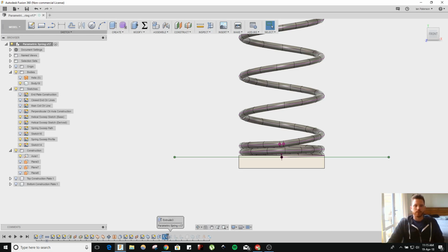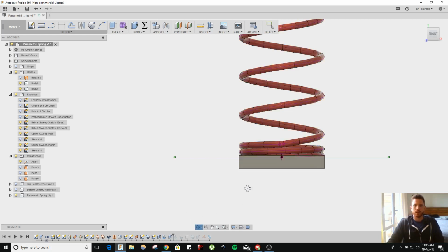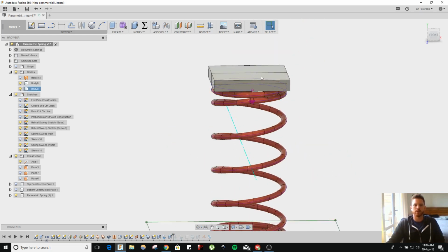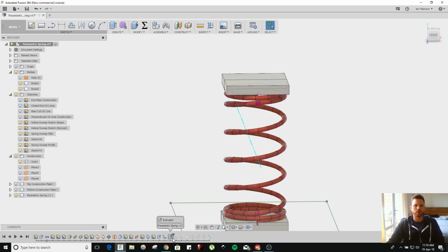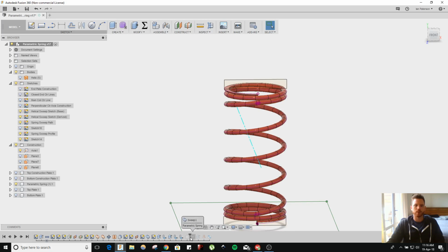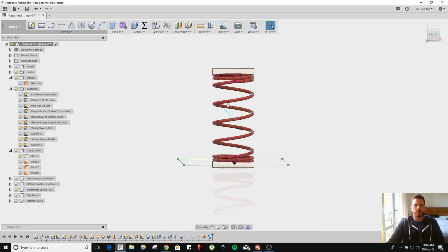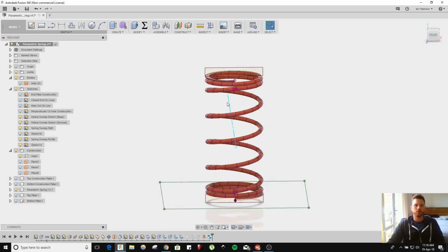More easily to the spring. So yeah, I then also just did an extrude to make, yeah, there we go. That's what I was just talking about. Make those parts. I just go through defining some components, and then what else? Oh, this is a different way I was creating this helix, so don't worry about those three things. And then I just grounded and made a rigid group. So that explains how I made a parametric spring.